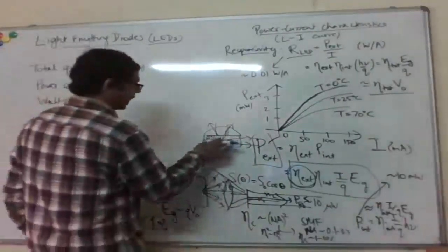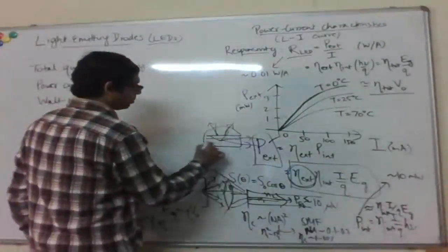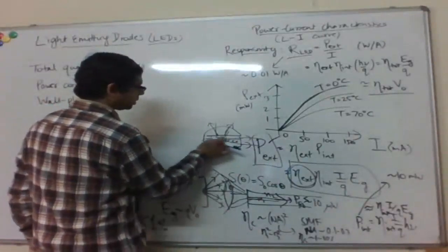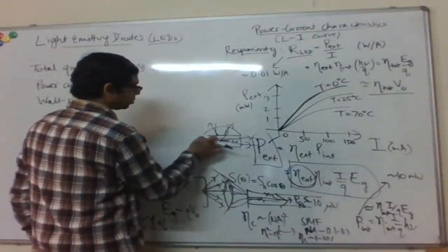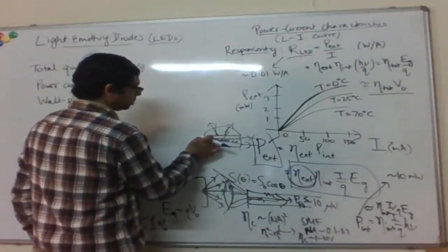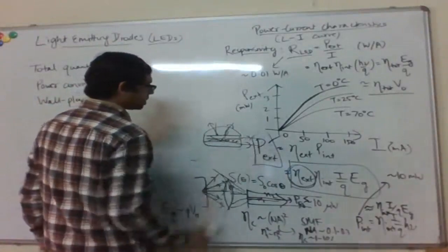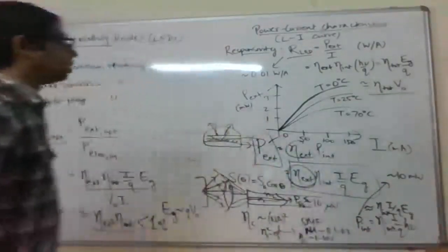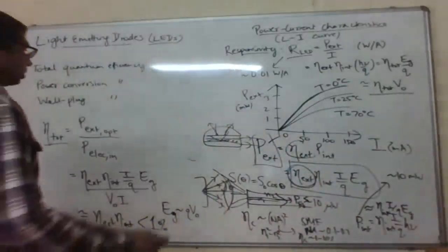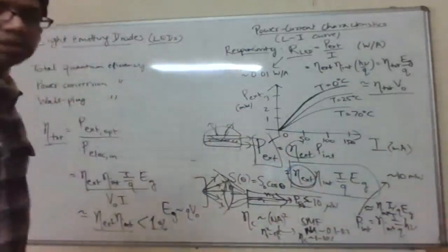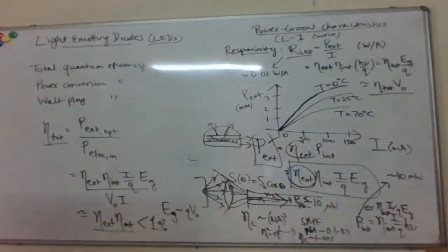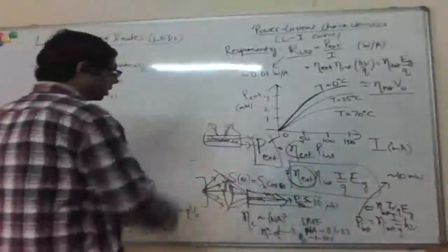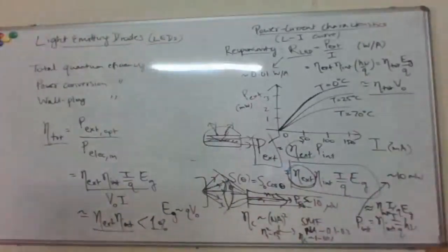You can also have edge emitting, where you now have a larger region contributing to the emission. So the external efficiency for the edge emitting can be slightly larger, and you can boost it again with external collection optics if you want to integrate them. But the absolute numbers depend on the particular LED.